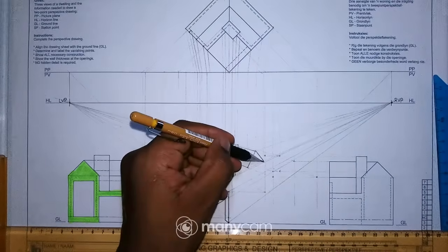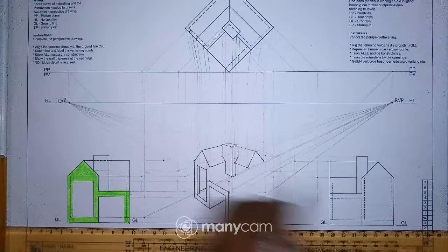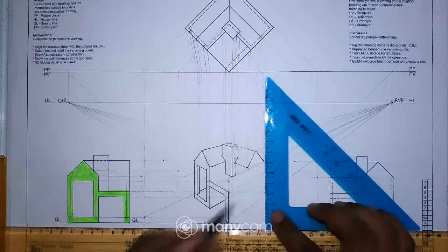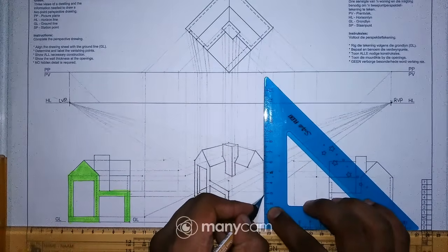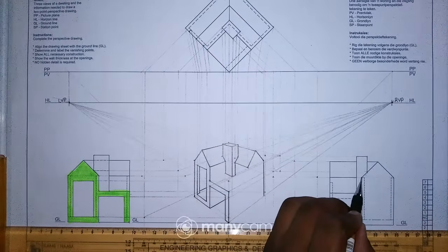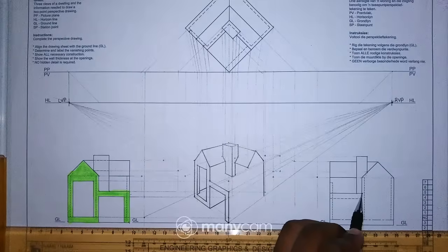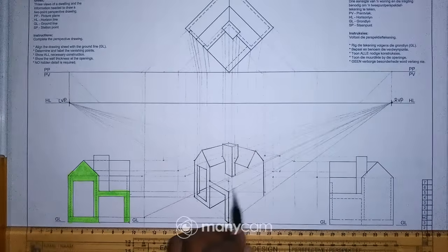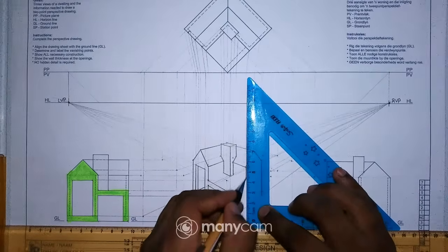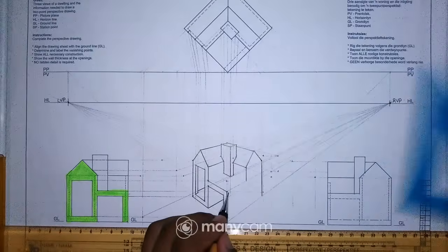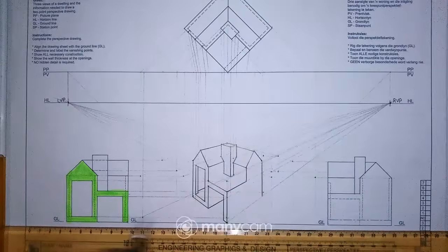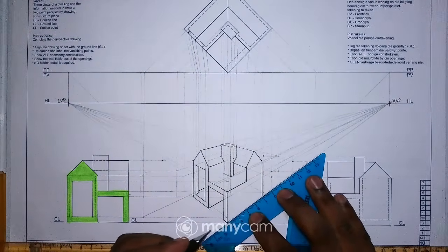Okay, I have to draw a vertical line. Why? Because okay, this point is this one, right? And there is what? A vertical line. So I can just draw a vertical line from that point there. So I'll just draw a vertical line, and then for this point, where is this point from the elevation? That point is right there, and we have a vertical line up to there, and this line is right there. It's this line. So what I can do is I can just draw a vertical line up to that line and then connect these 2 points. So just connect those 2 points like that, and then draw this ground line there.